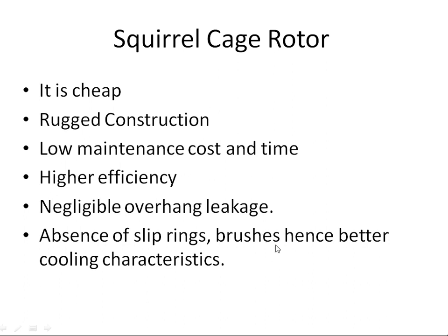Again, since there are no hot spots as far as brushes and slip rings are concerned. We'll have hot spots due to the friction occurring between them, as the slip rings are rotating and brushes are stationary. So the slip ring motor has a larger heat production as compared to the squirrel cage. So the cooling characteristic is much better as far as squirrel cage type rotor is concerned.